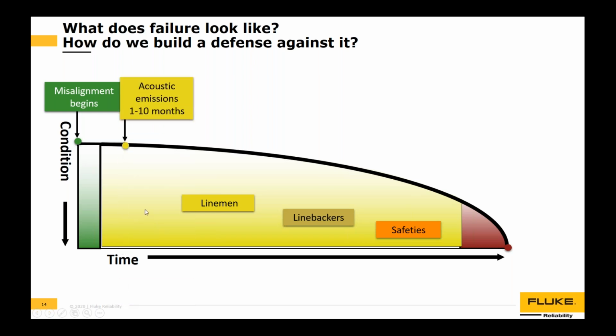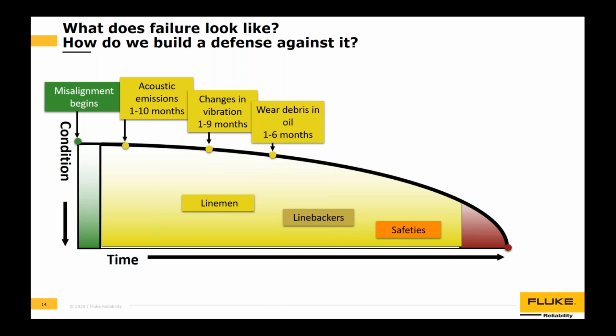Well, so how does that impact from a reliability standpoint? You know, we have acoustical emissions that you can pick up things several months in advance. Vibration analysis, several months in advance. Oil analysis, looking for the quality of the oil, impurities, wear, debris, things like that. But those first three are your linemen. You're looking months out in advance in these when you see things. Therefore, you're really trying to stop it at the line of scrimmage.